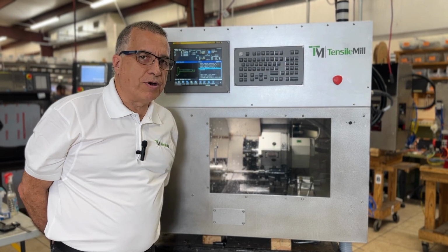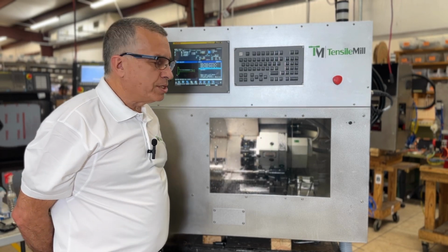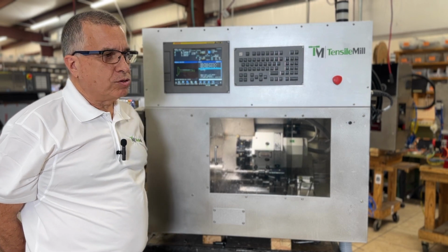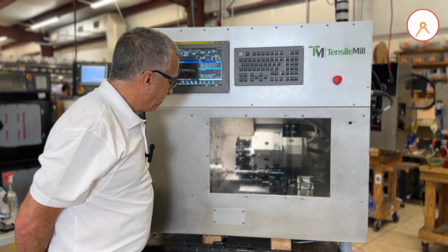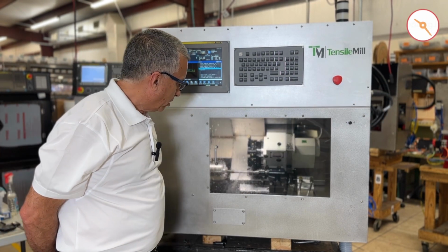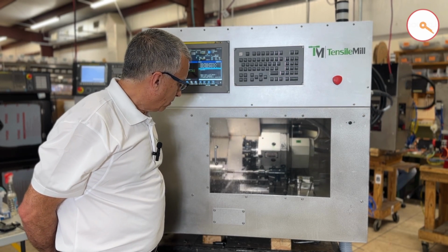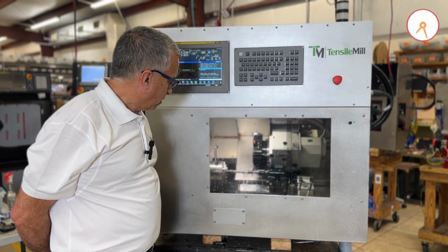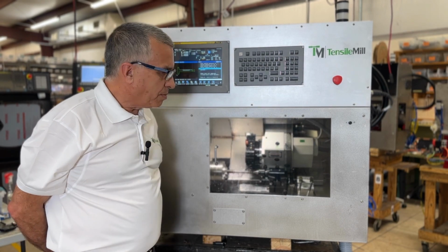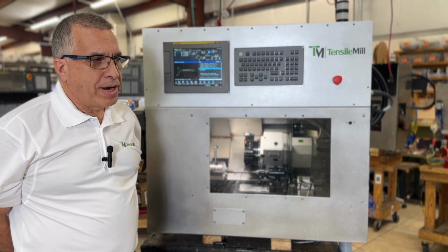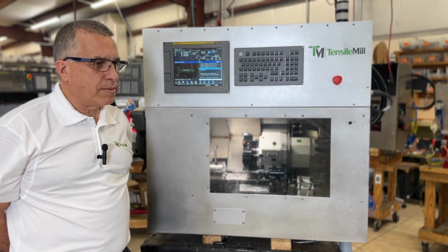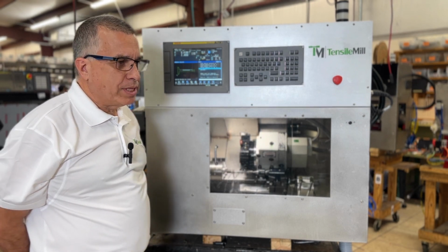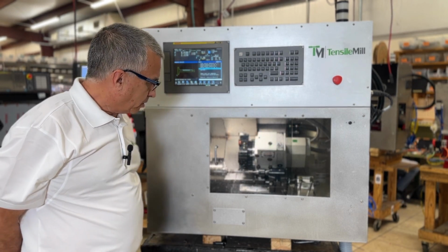Down to the 0.4 of the gauge diameter. Actually, a bit more than 0.4 because we're going to change tools and do the finish. Now we do a semi-finish. Semi-finish prepares the part for the finish, makes sure the cut is not too strong.